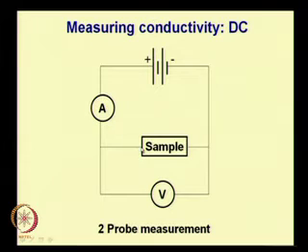But importantly, the location where that wire connects up to the sample, out here and similarly out here, just that contact point between the wire from the external circuit and the sample, itself has a finite resistance associated with it, which is referred to as contact resistance. So there is a contact resistance out here and there is a contact resistance out here.